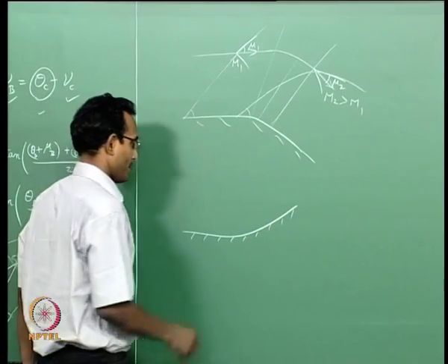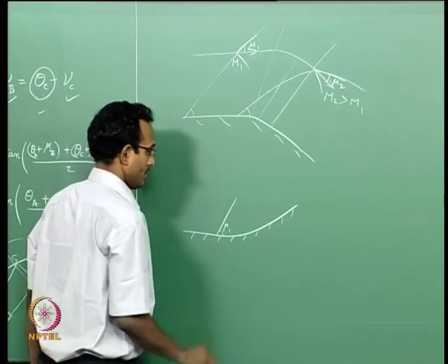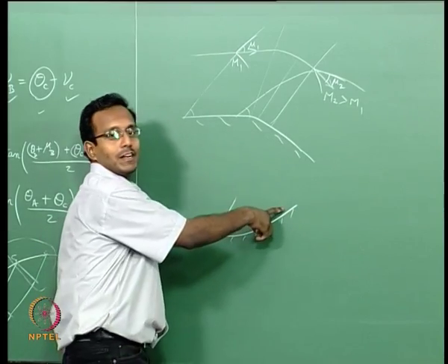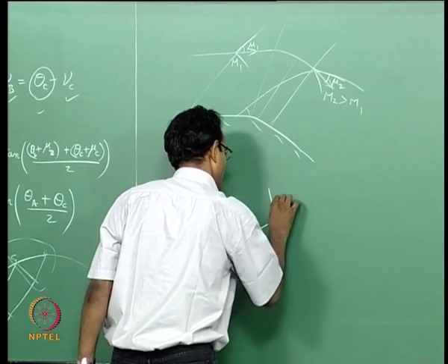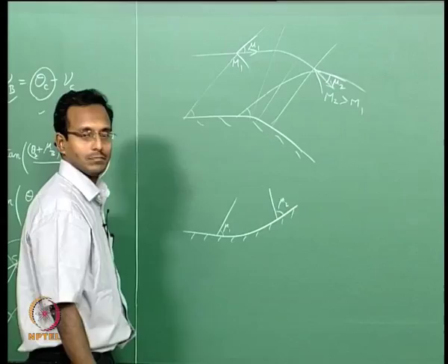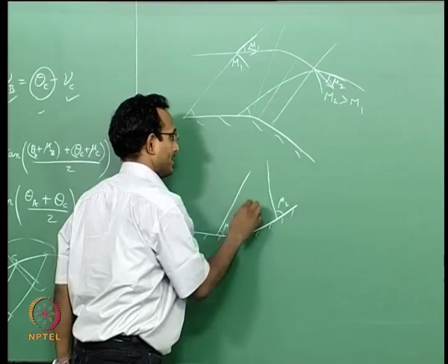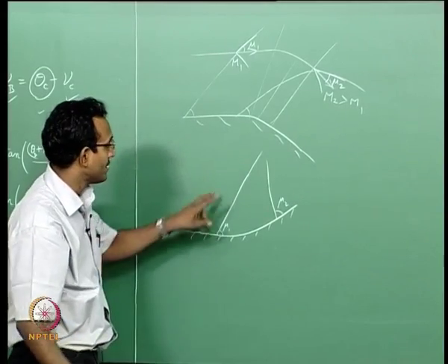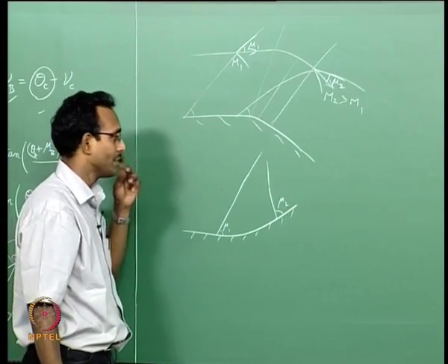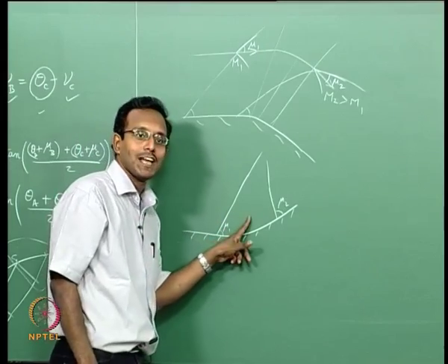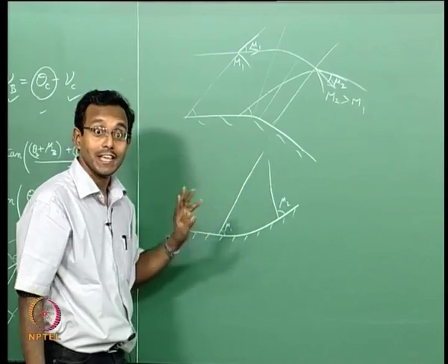Okay. Another way of thinking about it in terms of compression: I have, let us say, a compression wall. I have one mu1 here, but here we know that the Mach number decreases because of the compression. So, it will be a higher value. mu2 will be higher. Now what will happen, these two, they are both left running characteristics. If you look at it far away, they want to meet each other, that is what we will end up with. Okay. In case of compression happening in the flow, the characteristics will want to converge, the same family characteristics.